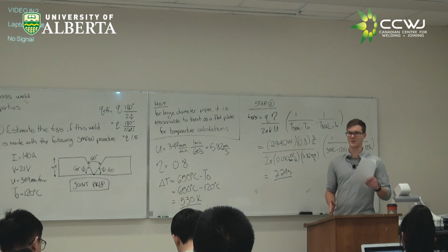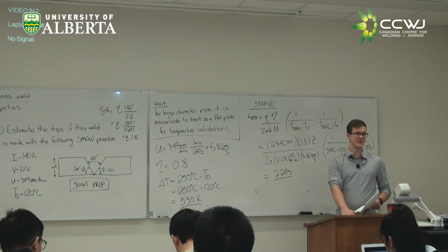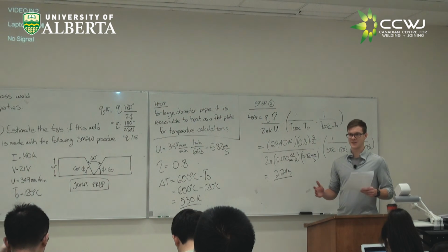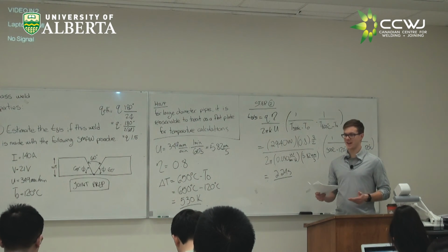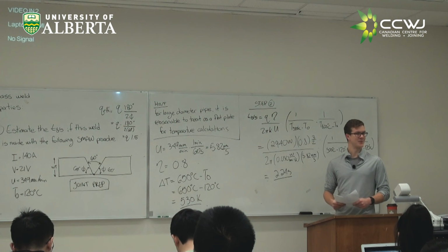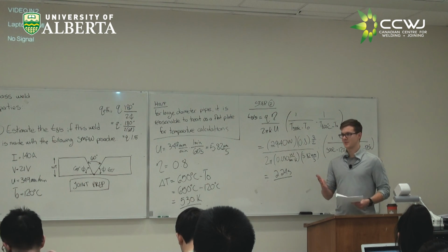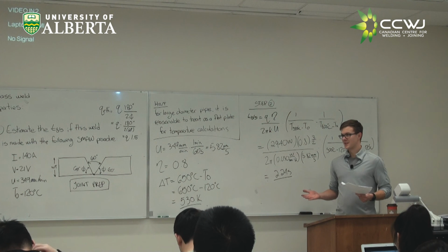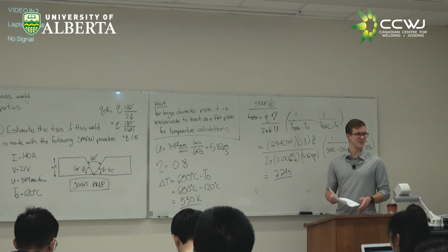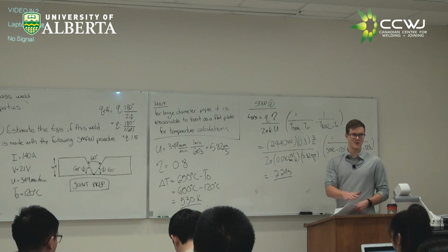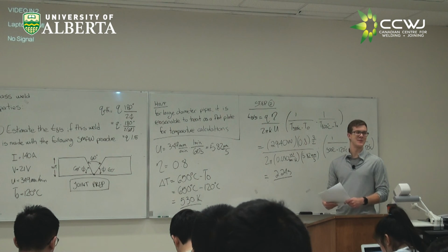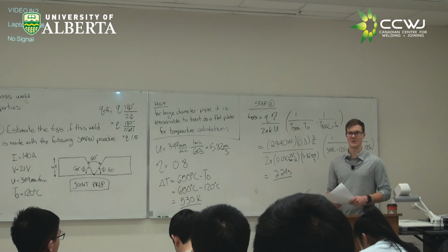You don't have to just believe it if the code says I can weld from this thickness to this thickness if I use this thickness to qualify it. You hopefully now have enough information that you can question that, and even if you end up with the same result, you can think about why you got there and understand why maybe it makes sense or maybe it doesn't, because the code is not necessarily an instruction book that's going to tell you exactly what to do. You can't do something if the code tells you can't do it, but it doesn't mean that if you only ever follow the code, you're never going to run into problems. There's always going to be some engineering judgment.